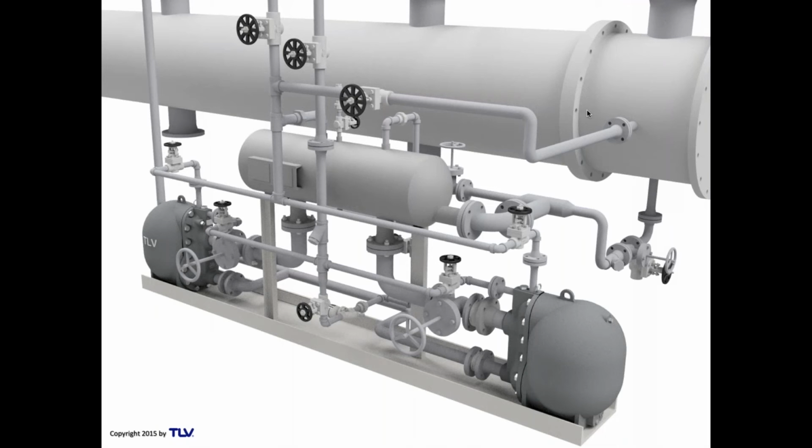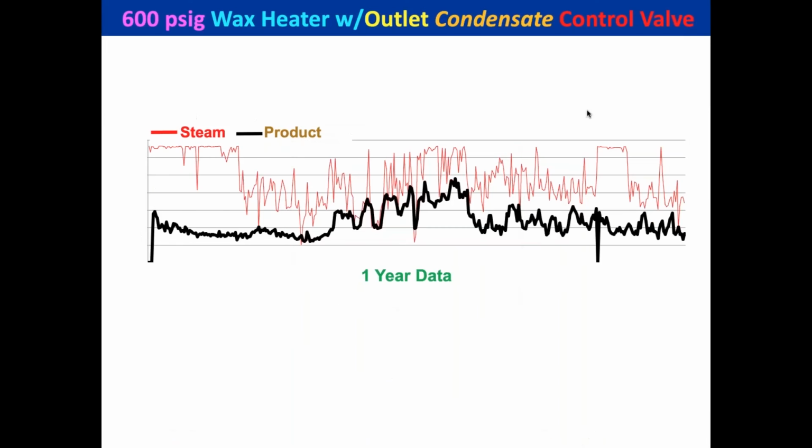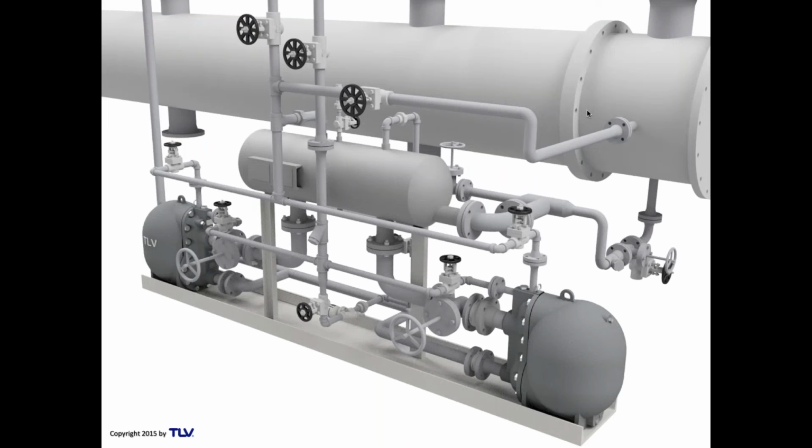One of the Steam collaborators today, one of the refineries, had a very tough, tight spot. So Justin McFarland put a custom system in there, where he went out and measured everything so it fit in a tight space for them. But you can fix these sort of issues. You don't have to have this problem with your channel heads and your reboilers and all that blowing through into the return header. And that's a pretty simple fix. Look at that. That's not a lot of pipe and pumps. It's 2 pumps and a little reservoir tank.